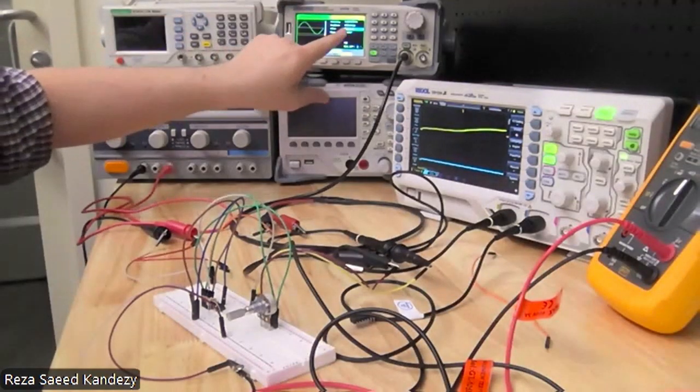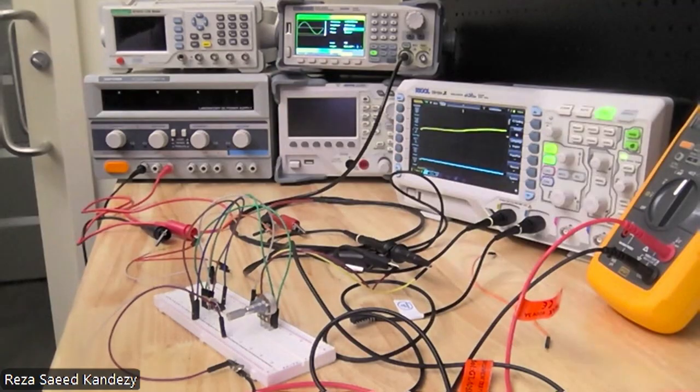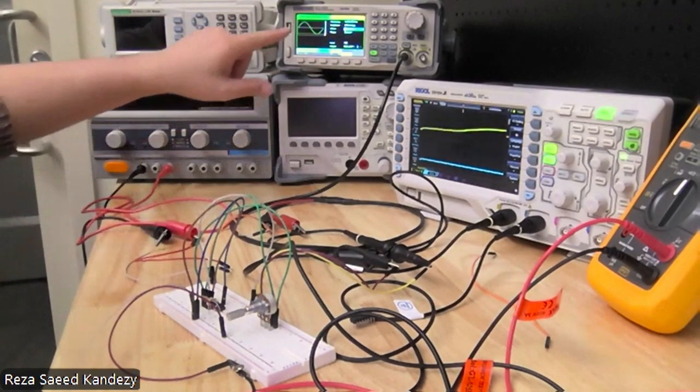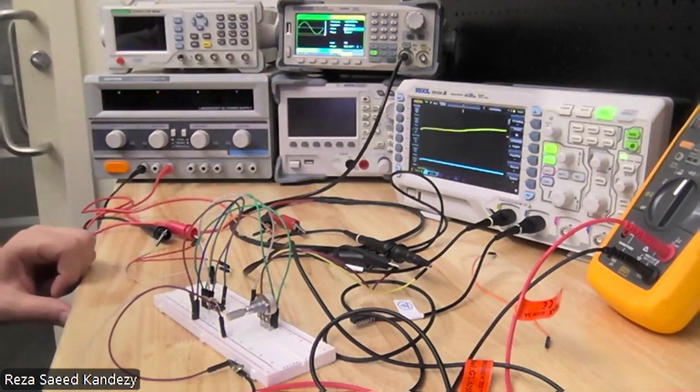Okay, now, as you can see, I have an offset here. I hope you can see that. An offset of 100 millivolt. Okay, the reason is that op amp input needs to be positive so they could trigger the transistor inside the op amp. Okay, so if you don't offset that, somewhere in the cycle you would have a negative voltage.